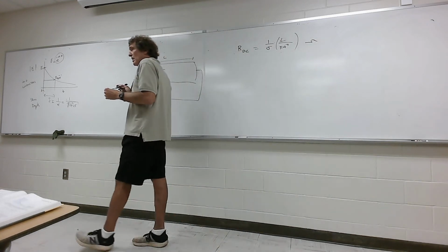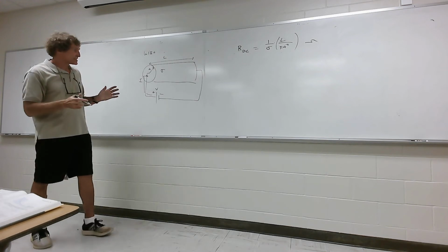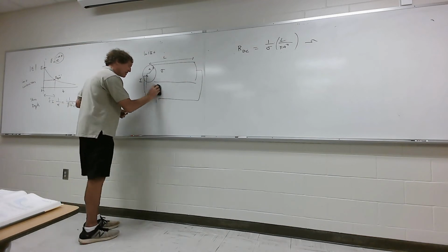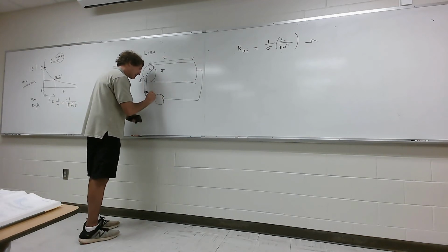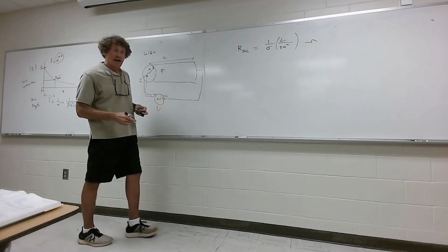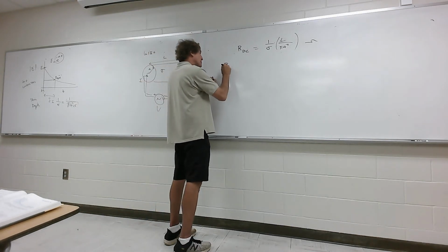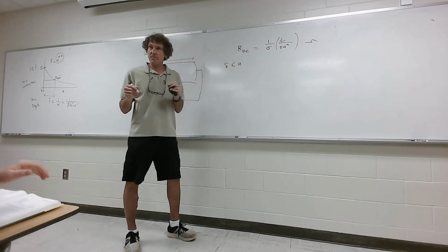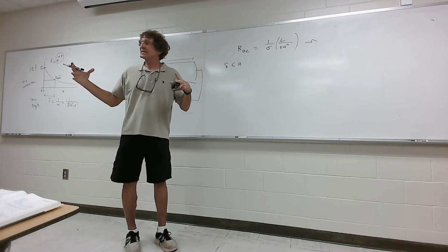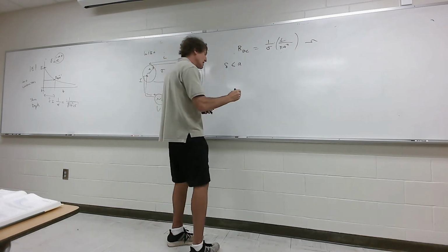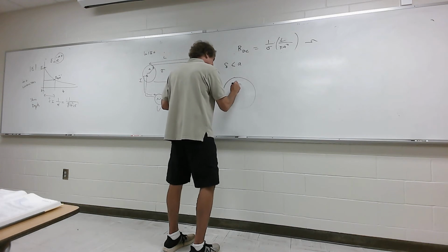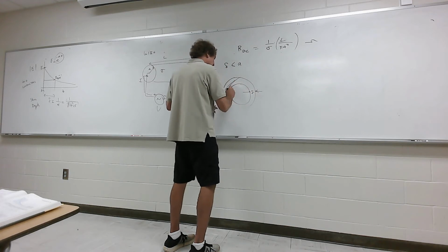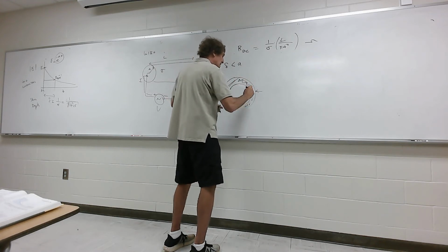Now, if all of a sudden we have an AC voltage there, not a battery, and that causes the skin depth to be less than radius A. All right, y'all follow me on this? Now what happens is all that current is confined to one skin depth into the wire. So the profile of current looks like this. Here's one skin depth, right there, and all the current, you can assume, is confined to one skin depth down.